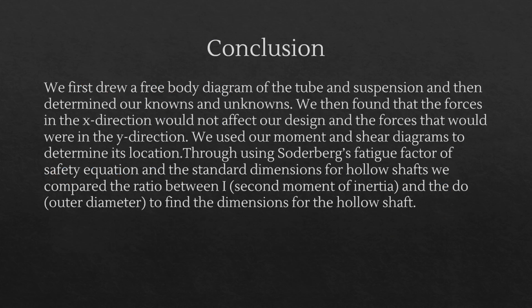This is our conclusion. We first drew a free body diagram of the tube and suspension, and then determined our knowns and unknowns. We then found that the forces in the x direction would not affect our design, and the forces that would were in the y direction. We used our moment and shear diagrams to determine its location.